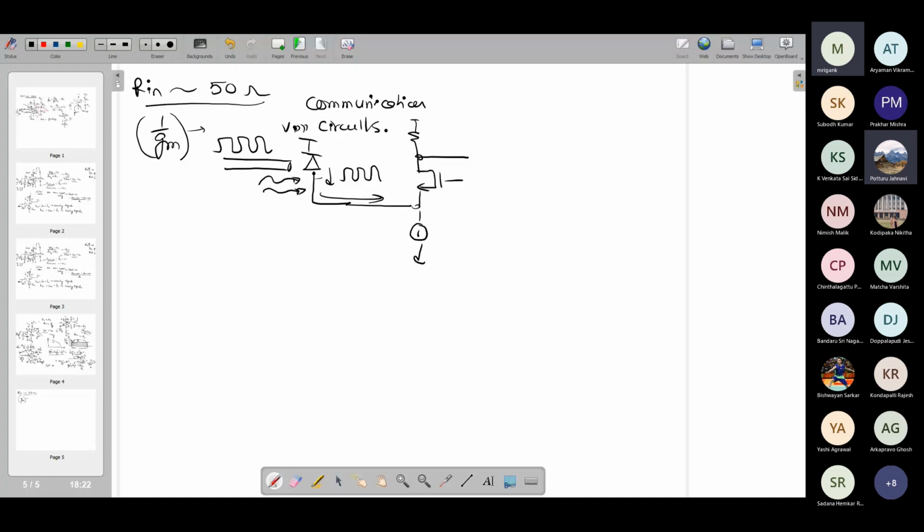In this case, the data rate requirement may be very high, of the order of 1 Gbps. That means you have to deal with 1 to 2 Gbps or even several Gbps of data. In a 10 nanometer... you can't achieve very high; at max, maybe 5 Gbps. Of course, with special designs and techniques like feedback, you may be able to go higher. People have achieved 10 Gbps, even 20. In lower technology nodes, the achievable frequency goes up, so people have been able to achieve even faster data rates.